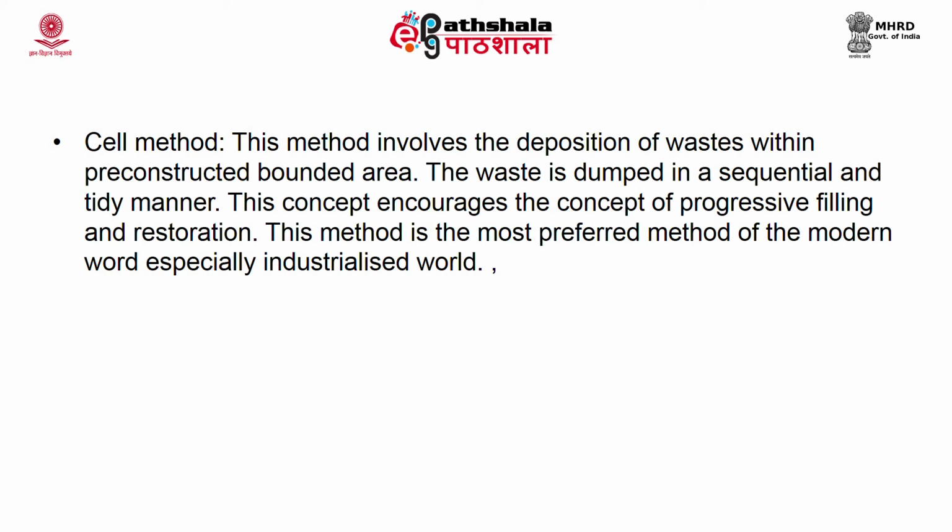Once one layer is over, then the second cell will be used for placing the waste. So, once one complete layering is done, the lorries will again bring the waste and start loading the waste in the first cell. So, a sequence is followed for the dumping or loading of waste into each cell.